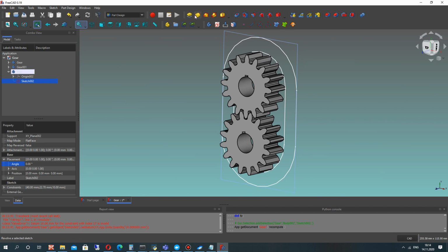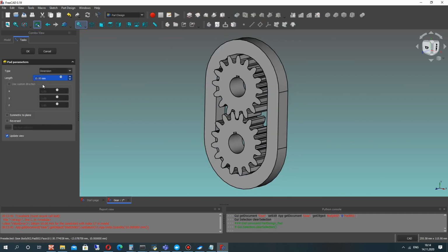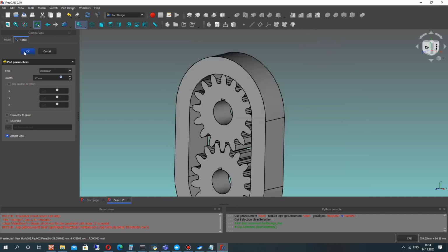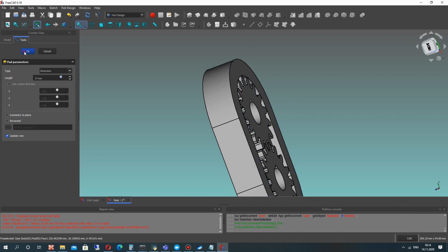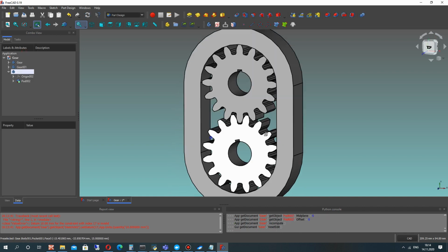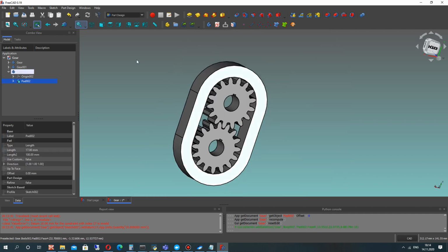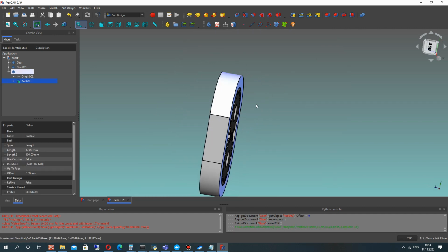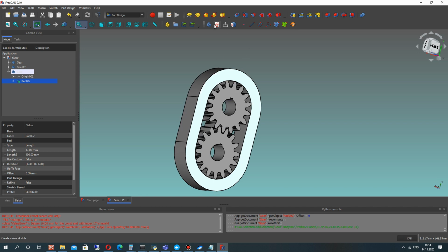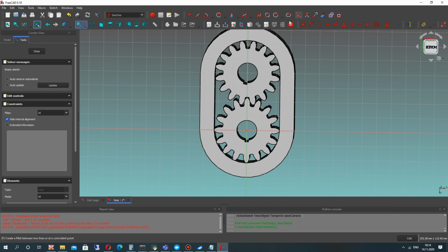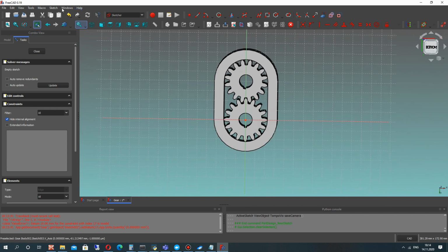After that, let's make the extrusion operation for our wall thickness. Set 17 millimeters. It's somewhat bigger than the thickness of the gears because we have to get the radial gap between the case and the gears here.